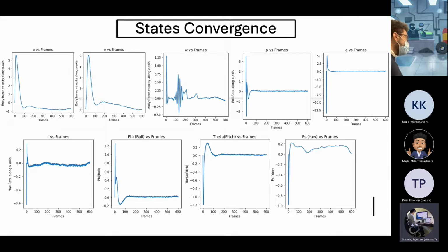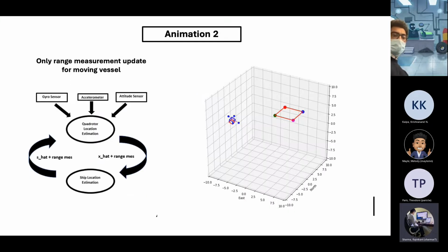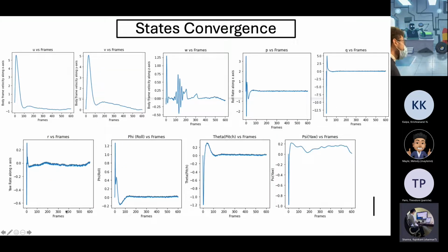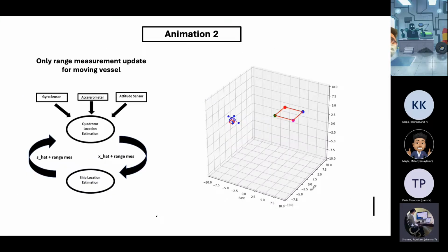These are the plots of the quadrotor, which is a rest to rest maneuver. All the plots are starting from 0 and ending at 0. So they were all estimated. The PQR we are getting from the gyro, and phi and theta from the LQR we are assuming. So all are estimated, UVW as well. A general good idea would be to also put the true states so you can see how close they are. Okay. So this is the approach we have done.